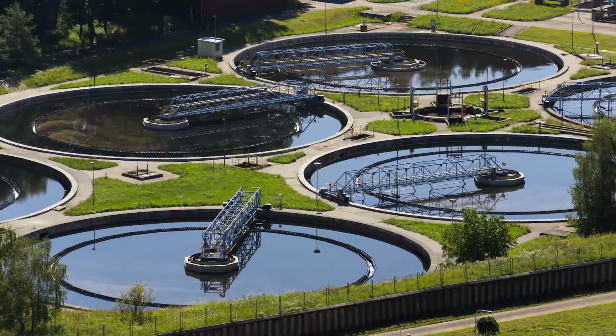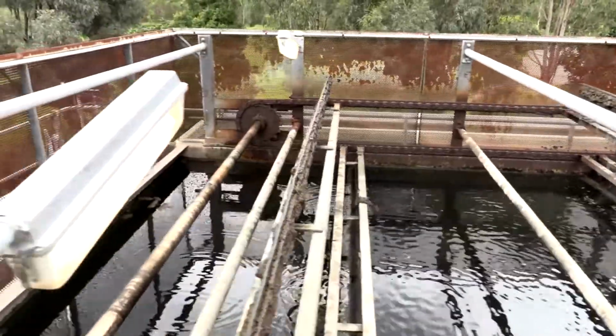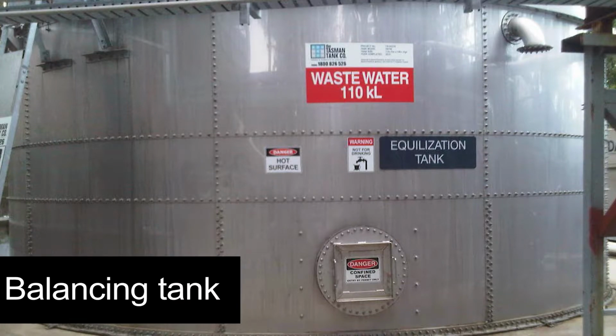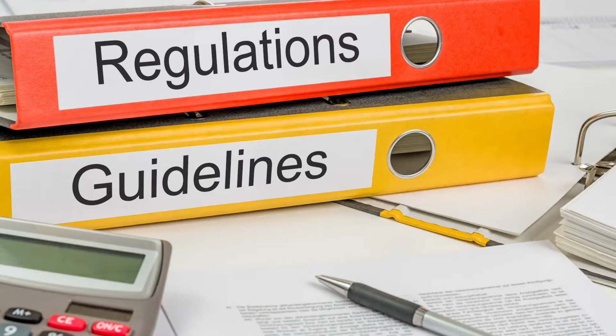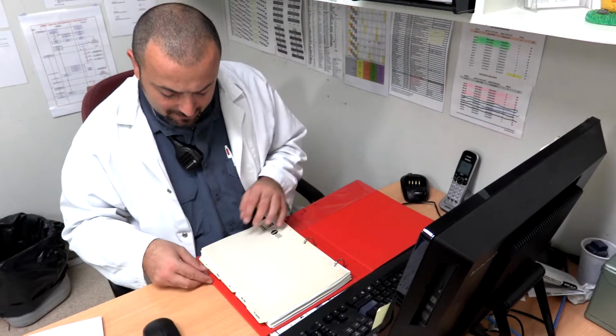Where wastewater is discharged to sewer via a chemically dosed DAF, more care is needed to provide a more consistent flow, so a large balancing tank is often used. The main challenges for balancing tanks are minimising odours, ensuring they are mixed to minimise solid settling, and minimising corrosion. If there are any regulatory requirements relating to primary treatment, these will be stated in your plant's Environmental Protection Licence, permit or approval issued by the state government.